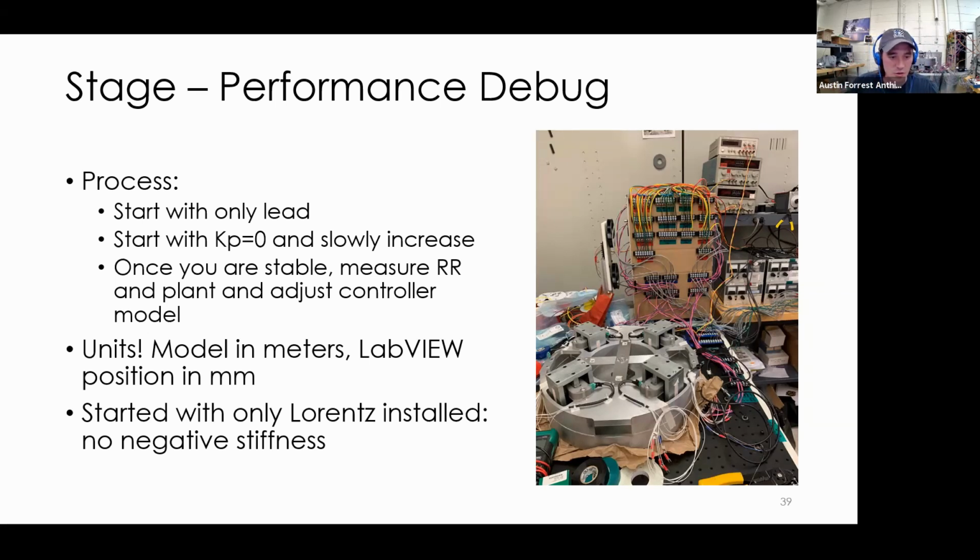When I first turned it on, it was just oscillating like crazy, did not match at all what I was expecting. It was actually Bridge who gave me the advice: definitely turn off your lag filter. Your integral is adding DC gain, but at the cost of reducing your phase, which you don't want when you're just trying to stabilize the system.